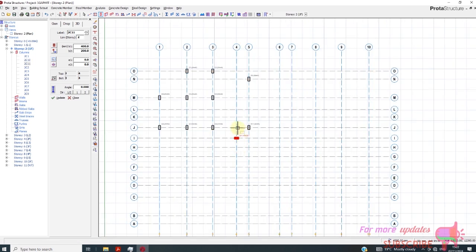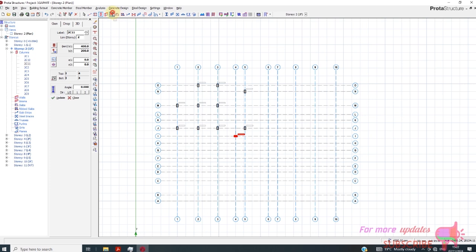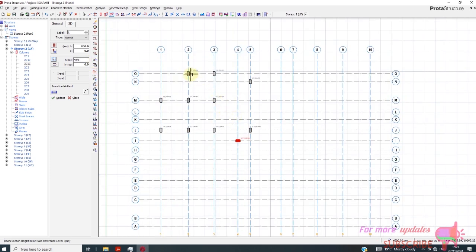Okay. So I'll activate my beams. General. 200 by 450. Okay, so I'll start that. Right click to release from there.